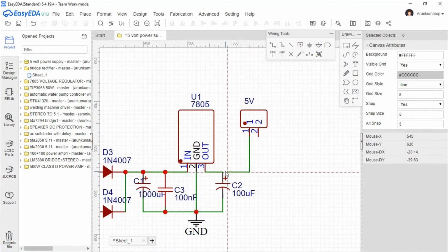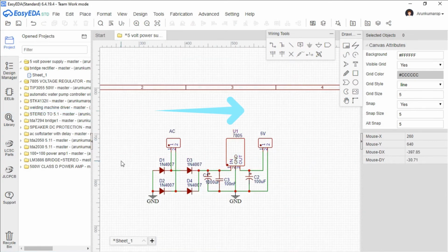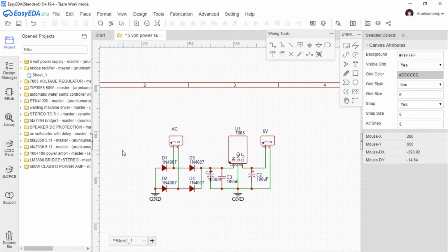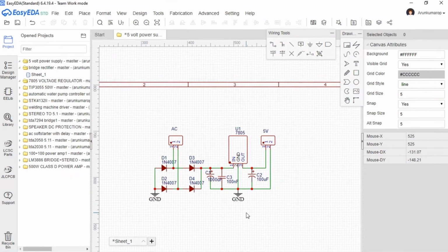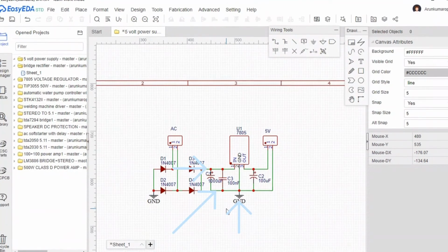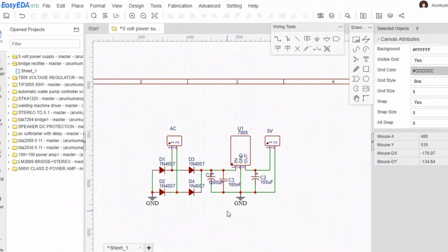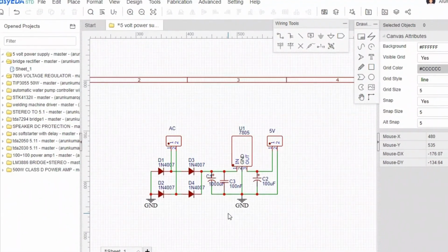Good practice will have signals flowing from inputs at the left to outputs on the right, with electrically important sections drawn correctly, the way the designer would like them to be laid out on the PCB, like putting bypass capacitors next to the component they are meant for. Little notes on the schematic that aid in the layout are very useful.